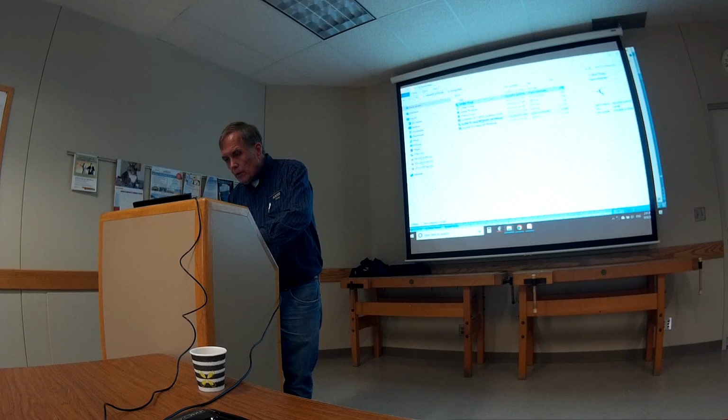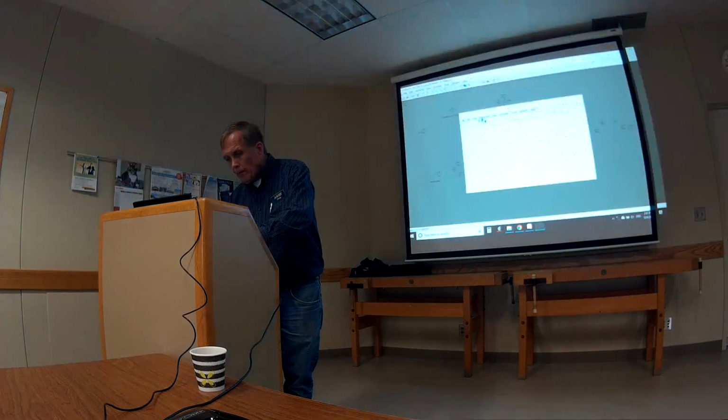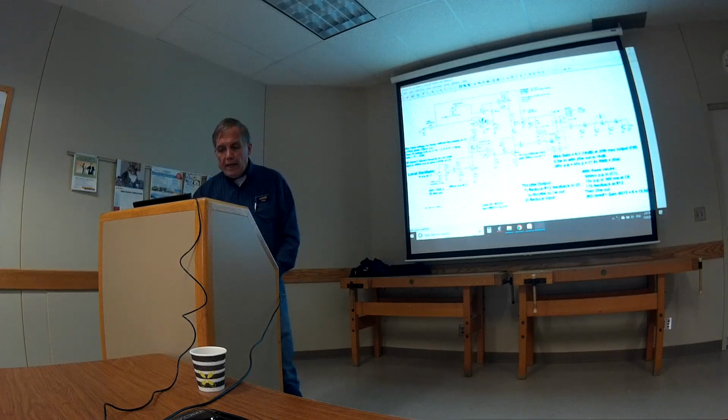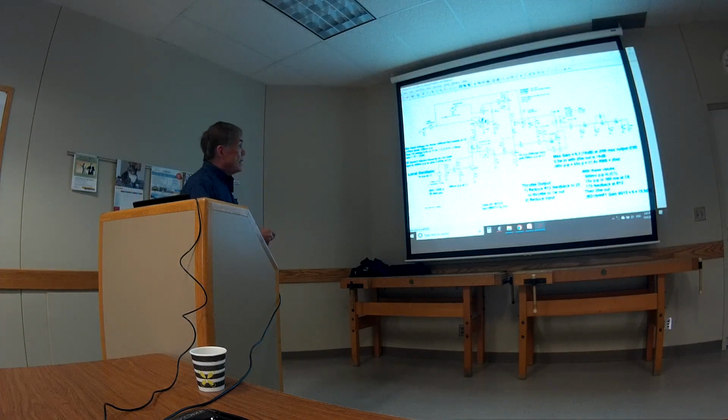And I just want to show you one other little transmitter very briefly. It's a little more complex again, but here's a local oscillator, and it's just a little buffer, and a transformer coupling, and the key mechanism up here is a little bit more complex because it's 2 different stages, and it's trying to shut it off really early as well as late.